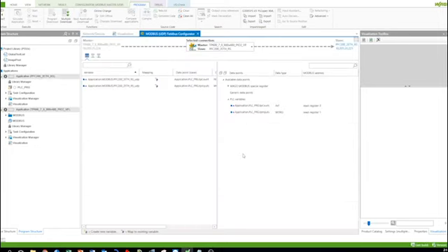For the PFC200, the configurator allows me to select from a list of variables from the PFC200 project and map those to the Visu panel. Once the variables are mapped to the Visu panel, I can then assign those variables to different objects on my visualizations, such as the counter value and the pilot light.